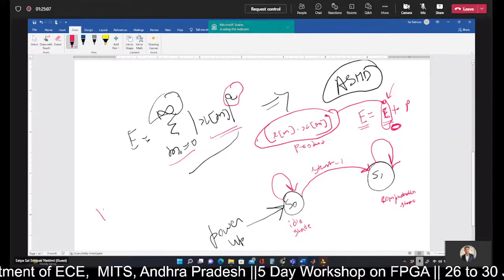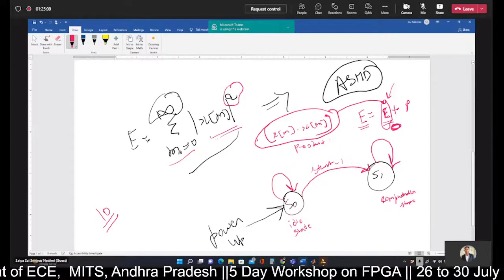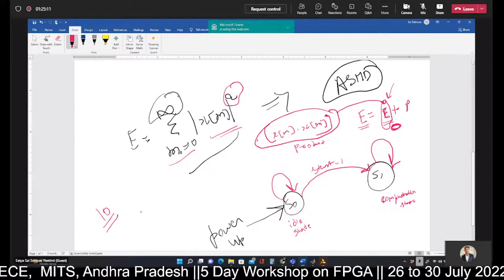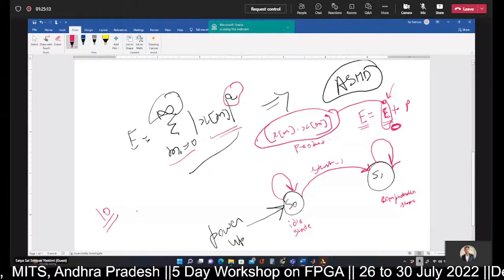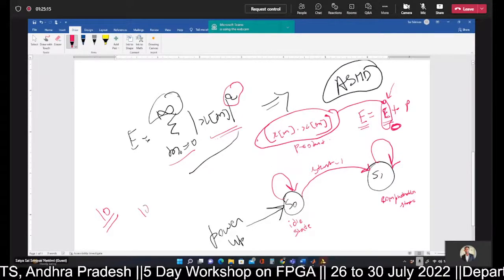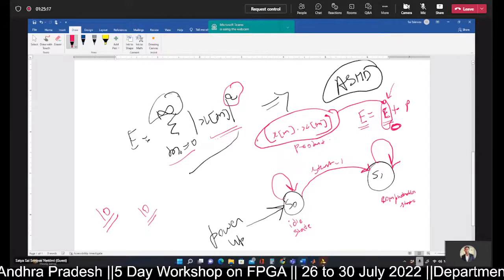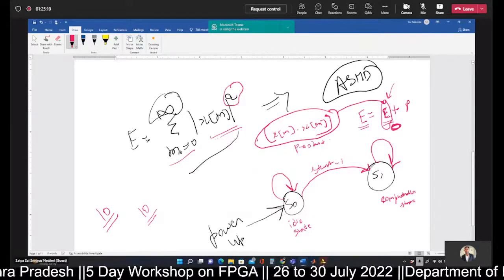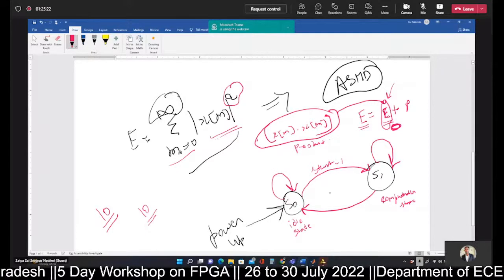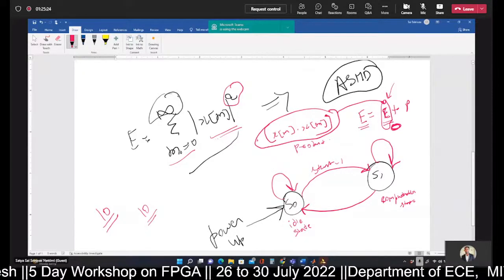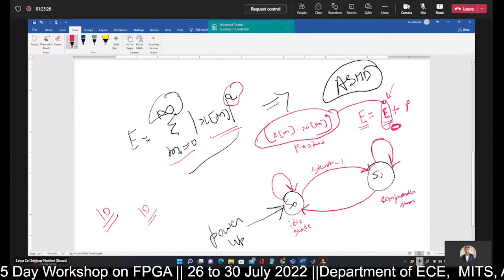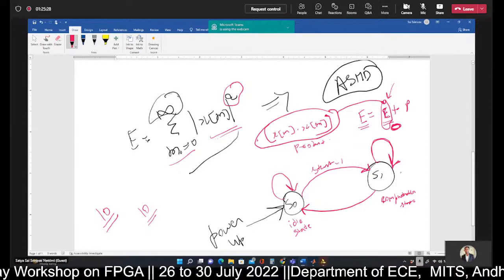Say, for example, we have a frame size of 10. After computing the energy using 10 frame samples, only then should the FSM switch from the S1 state to the S0 state. In all other cases, it has to remain in the S1 state in order to do the computation.